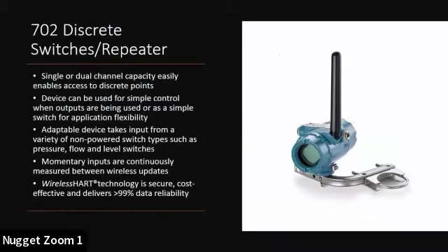Oftentimes you'll need to flush daily, every other day, something like that. You can do this remotely if that's allowed. And then your information on your flow will also indicate that the flush worked. We could see that it happened, and then shut it down and you'll know that it's actually closed. So you've got that feedback loop going on. That's important to keep your lines clear.